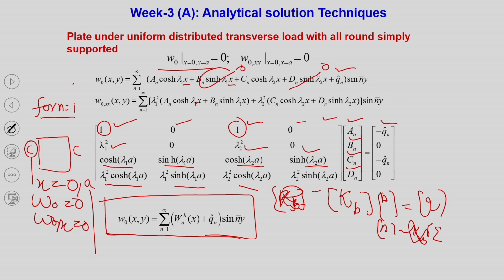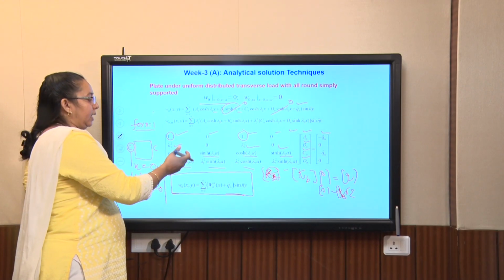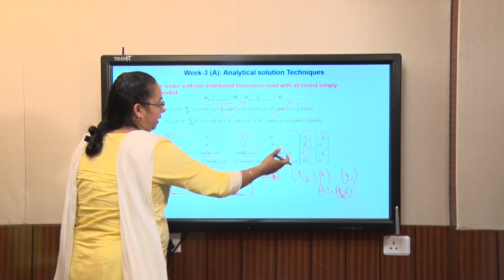Similarly, x is equal to a. For that you will have some different kind of constant and you can evaluate. In this way you have learnt how to develop a Levy solution for a plate. For any boundary conditions one can develop it, so one needs to know this matrix.